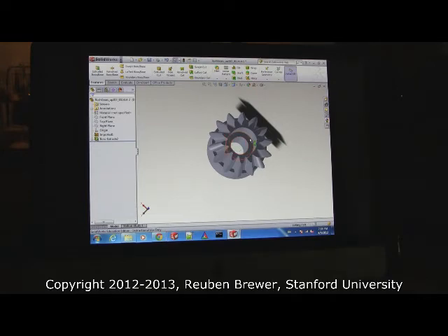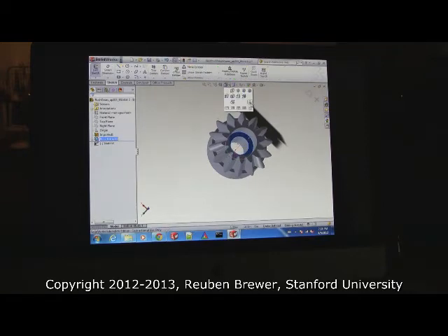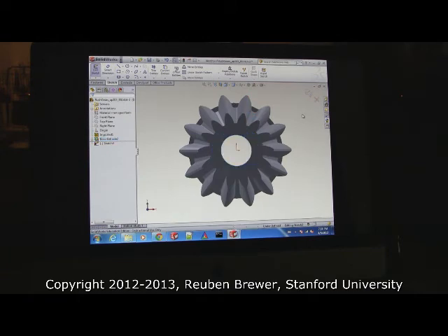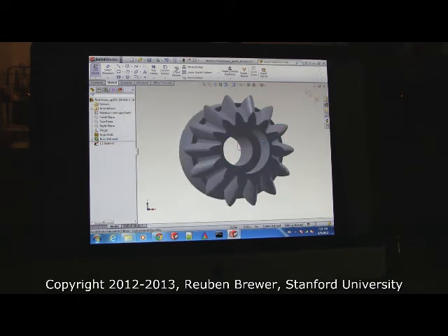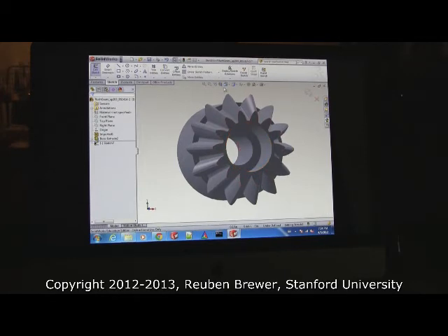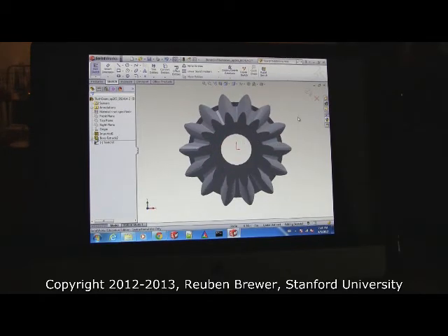Okay, next thing. Can you see my screen? Select that surface. Extrude. Make it normal so we can see it. Now rotate your part a little bit, and you see how there are two circles in terms of this surface and this surface? Now, when we go back to normal, it disappears. You can't see it. It's bad.